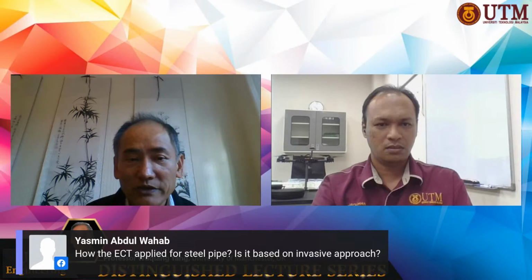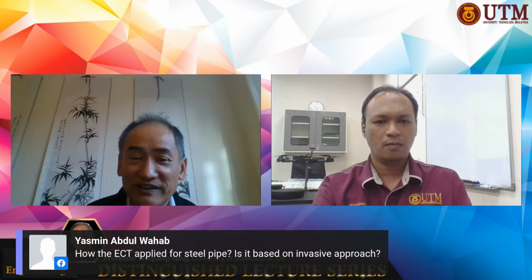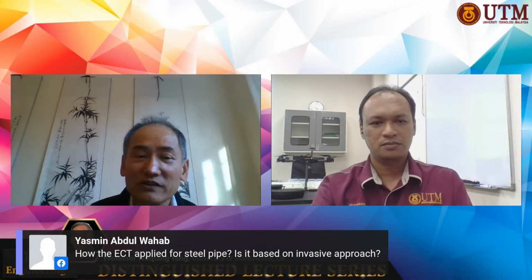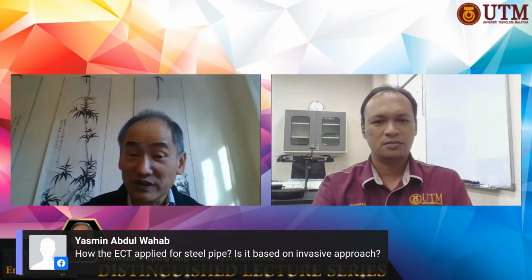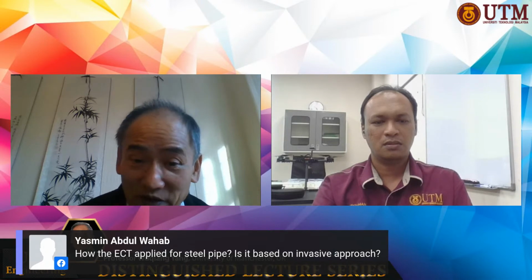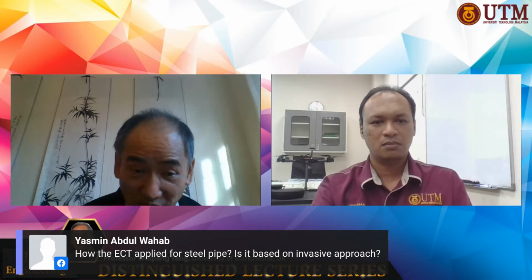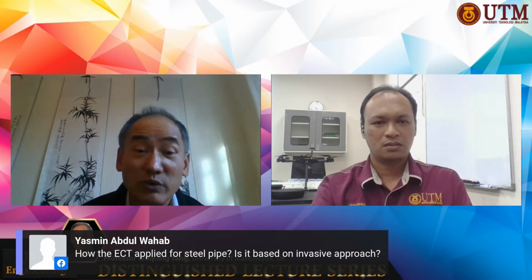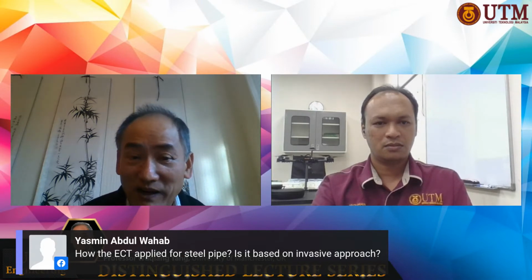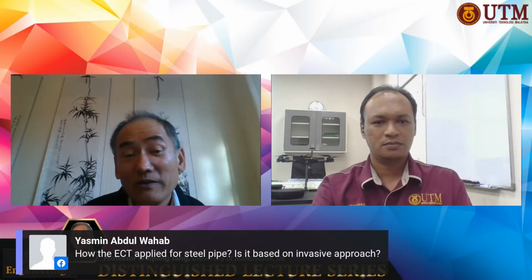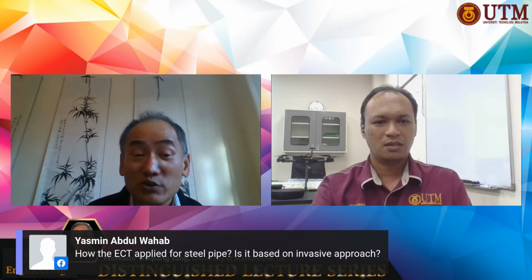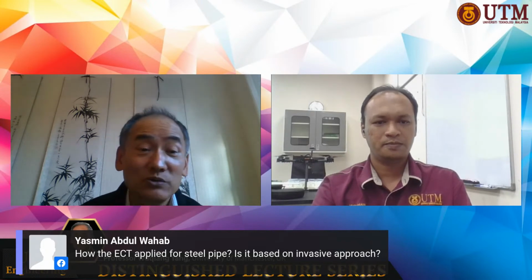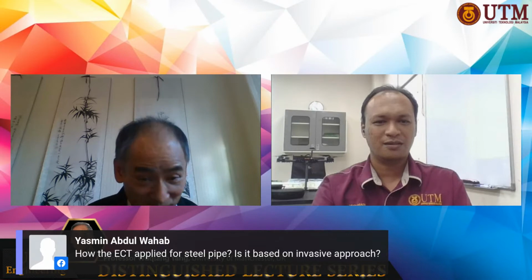We have made several sensors of this type. In principle, you can't have a capacitance sensor just outside of a steel pipe. You have to put electrodes inside. You make your sensor like a sandwich in a steel pipeline. Basically, you need the insulation layer and put the electrode inside. But we know how to do it. In engineering, it's doable.